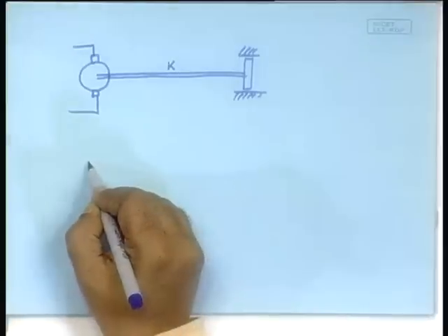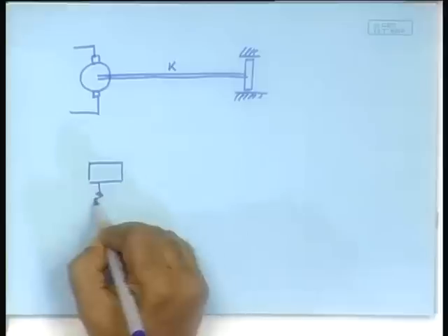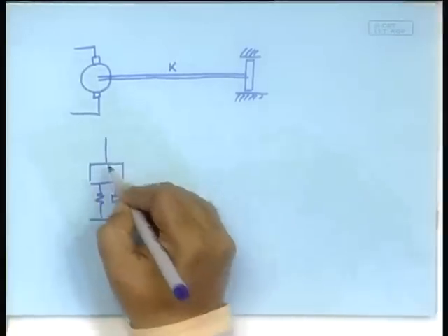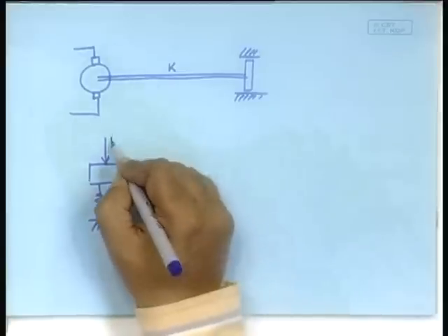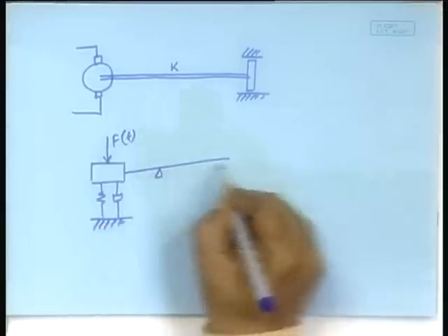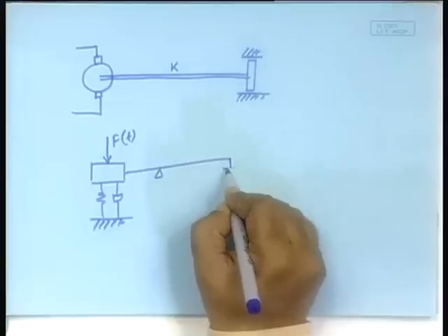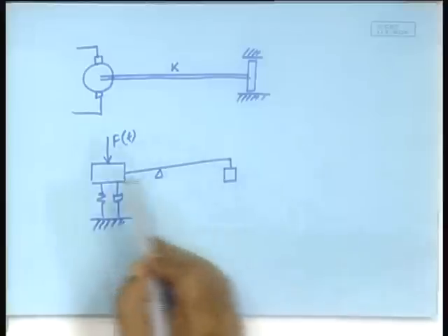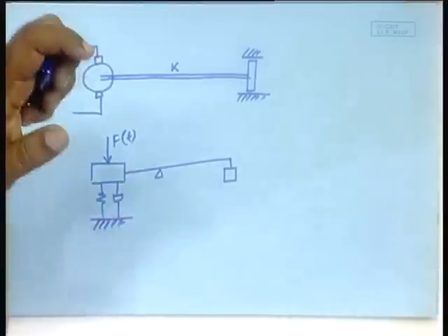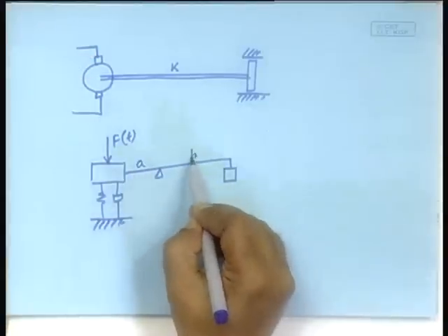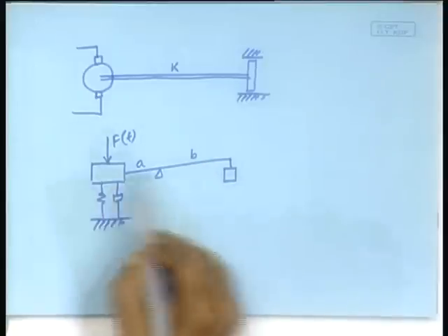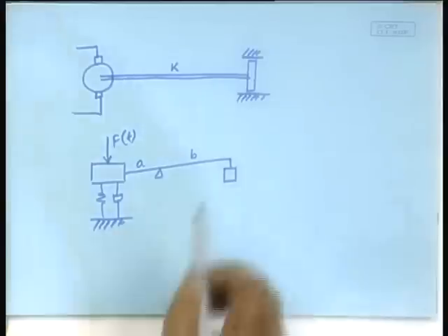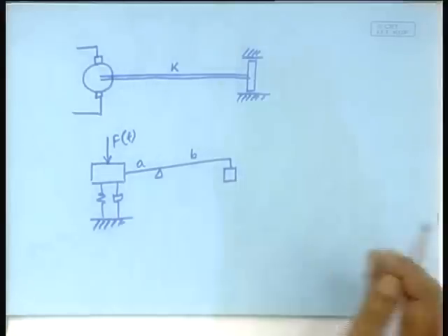Imagine the situation where you had a mass with a spring damper arrangement here and well anything there. And then, now suppose you have a mass directly connected here, then what happens? These two masses, though they apparently are located at quite different places, do not have their own degrees of freedom. Why? Because if this fellow goes up, this fellow will have to go up and down exactly in the same way, right. So, they do not have any independent degree of freedom.